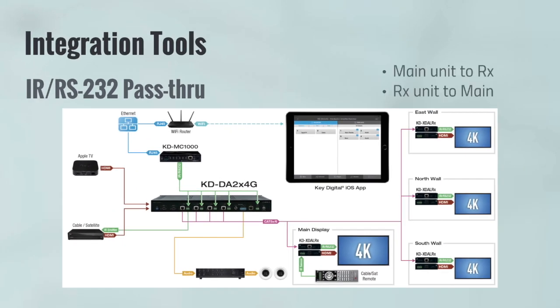Now, in addition to passing through to control the monitor connected to the HD-Base-T receiver, it is possible that you can collect line-of-sight IR or RS-232 at a connected RX unit and have that be output at the respective 3-pin Phoenix so that you can control a connected device in the equipment rack near the DA2x4 or 2x8G.